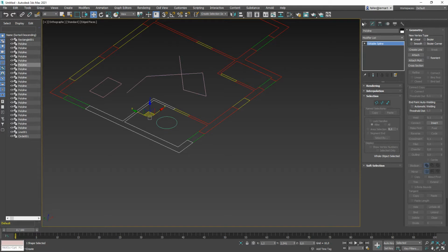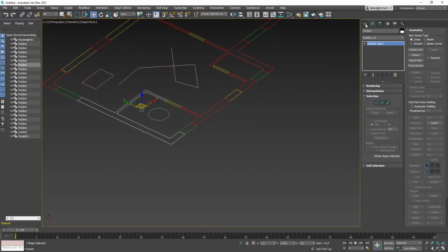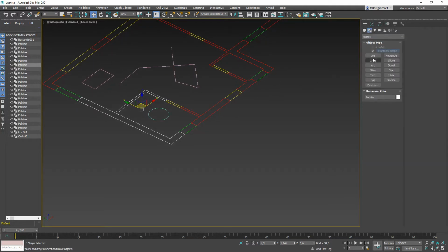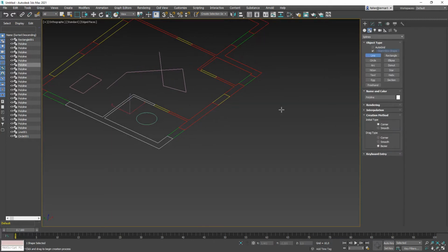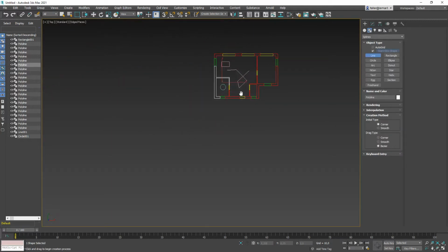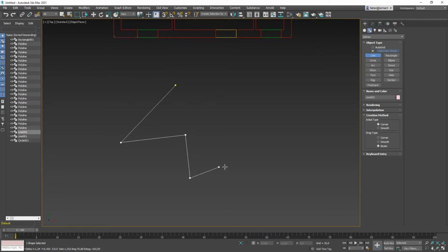And the first thing is we are going to repeat once again what's the difference between a closed and an open polyline. So when I use a regular line tool, and again I'm looking from the top and draw a few things here. If I use a line tool and I draw any shape, if I click with the last vertex onto the starting point, it will ask me, do you want to close? Yes. That is the best way, of course, because now I have a closed polyline.